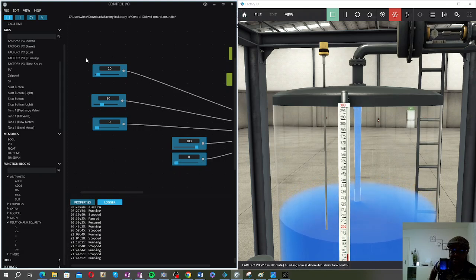Not every industrial process can be reproduced mathematically, but there is software, and systems like Siemens have incorporated the ability to automatically tune the controller, generating the proportional, integral, and derivative gains for you. You put them in, and to a large extent it will control the system.